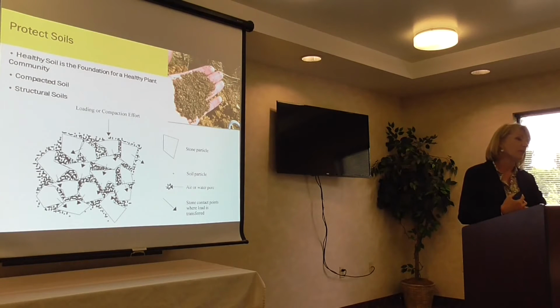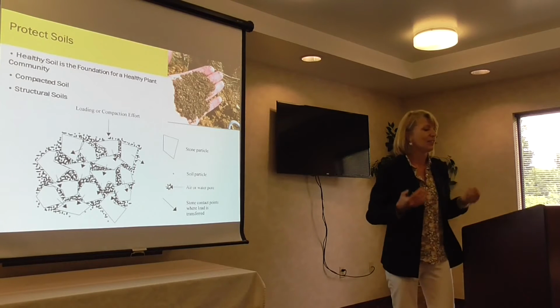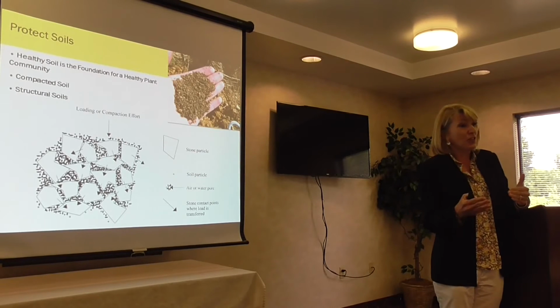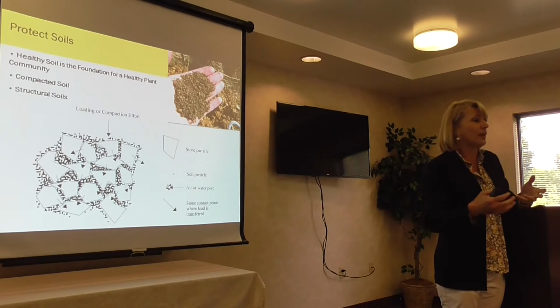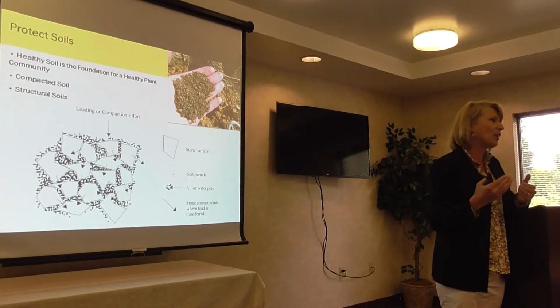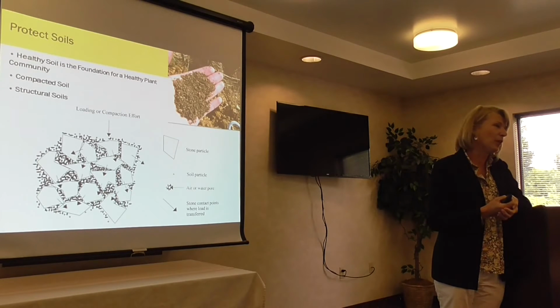That's probably one of the biggest issues we have with establishing, especially these bioretention areas and areas where you want to have infiltration occur, is that during the construction process, they start driving machinery across these sites, and it just seals it up. And it's a challenge, and again, a little preventive work, making sure that your contractor understands, knows how to go in and work from the edge to excavate, knows that they shouldn't be driving across it because there's a lot of cost and expense in going back in and remediating, especially the soil.